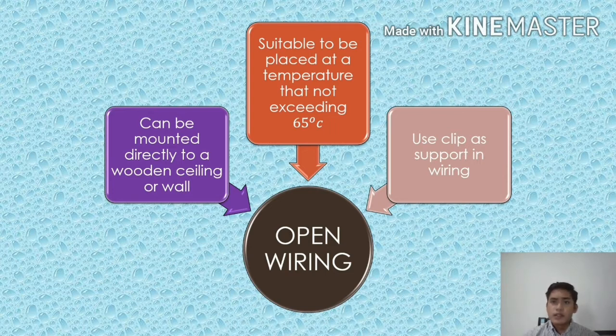Third, this installation uses clips as support. It is material that supports the cable so it does not hang and looks neat. But make sure the clip is not made from iron because iron is able to conduct electricity.